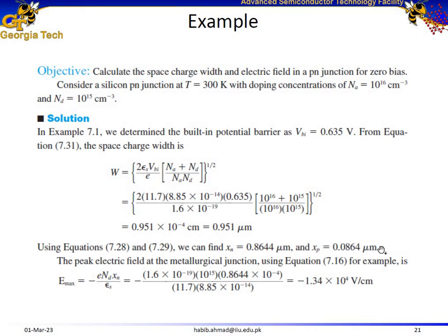I want to show you a relationship between the doping concentration and the depletion width. So which of the depletion widths is higher, Xn or Xp? I mean, you have the values, right? Xn. Xn is higher. How about the acceptor and donor concentrations? Which one is higher? It's given in the problem statement. Which concentration is higher, acceptor or donor? Acceptor. The acceptor concentration is higher, but the depletion width on the P side is lower.